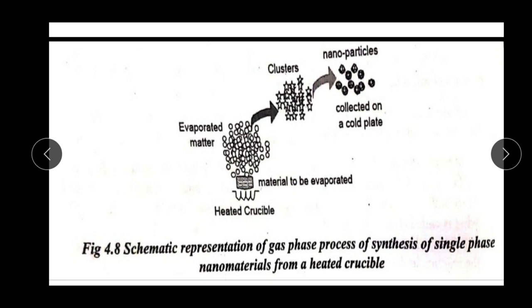In homogeneous CVD, particles form in the gas phase and diffuse towards a cold surface due to thermophoretic forces, and can either be scraped off the cold surface to give nanopowders or deposited onto a substrate. In heterogeneous CVD, the solid is formed on the substrate surface, which catalyzes the reaction, and thence the film is formed.